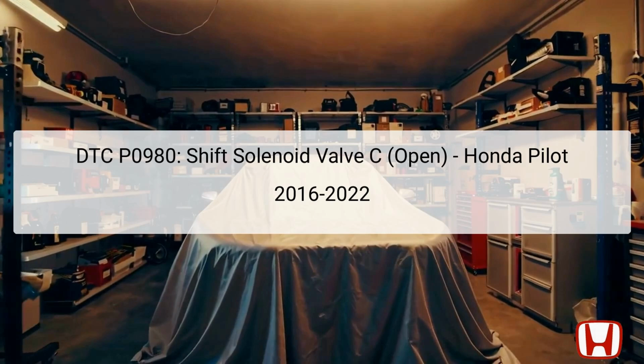The DTC Diagnostic Trouble Code P0980 relates to the Shift Solenoid Valve C, indicating an open circuit in its functionality. This error suggests a problem in the electrical circuit associated with the valve, preventing the transmission from shifting to specific gears, namely the second and fifth. It is vital to note that this issue cannot stem from mechanical faults within the transmission itself, but is solely electrical. The PCM, Powertrain Control Module, stores this code and does not allow shifting due to the fail-safe mode activated